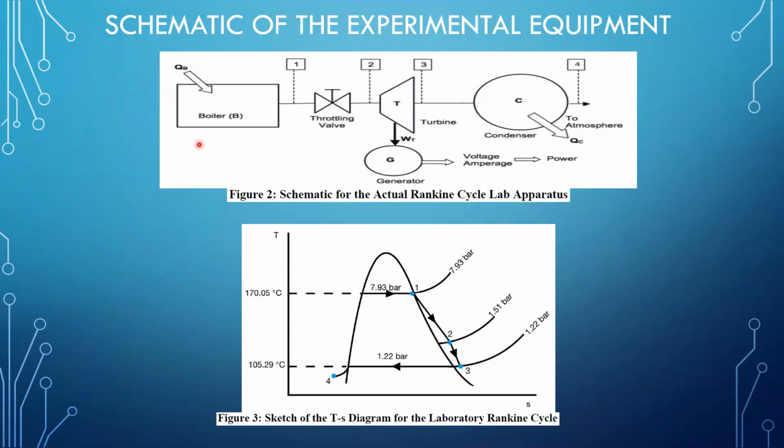Before we get to that, I will just go through each stage on top in the schematic as it relates to this chart. Now, in the boiler, there's water, which is a liquid. Now on this chart, we have 3 main regions. We have a wet phase or a subcooled stage, which is to the left here. Within this region, within the constraints of these lines, we have a 2-phase region, which basically means that we have both a liquid phase and a gaseous or vapor phase, where the liquid is undergoing a change in state to the vapor as it passes across here.